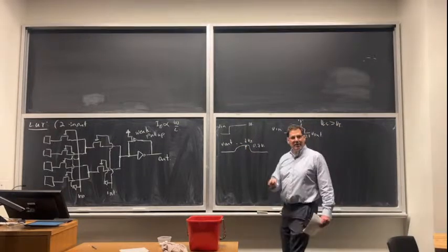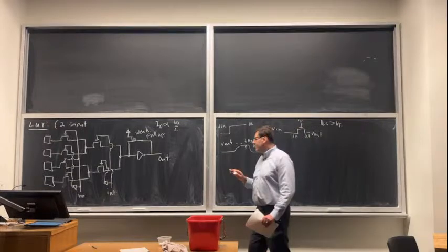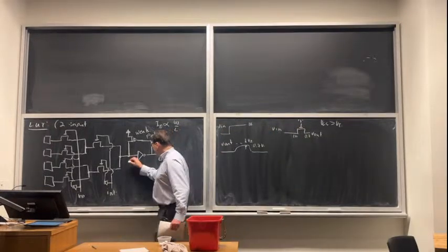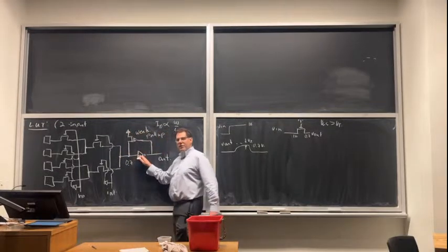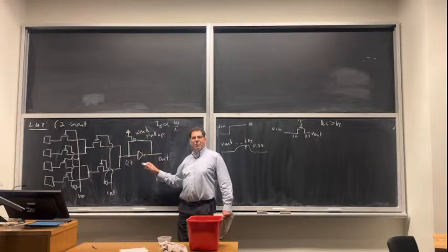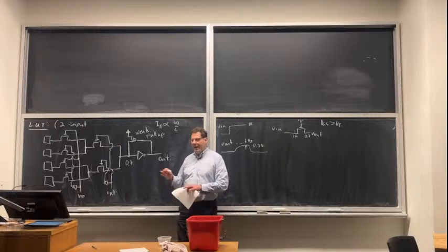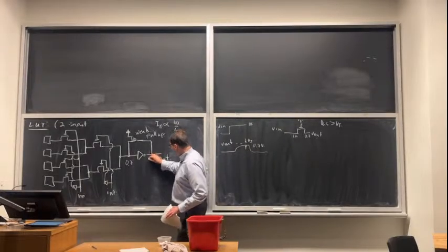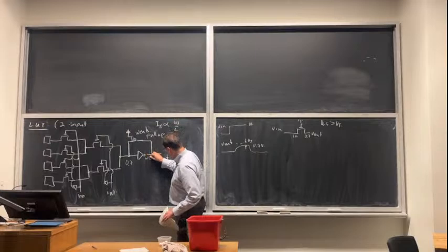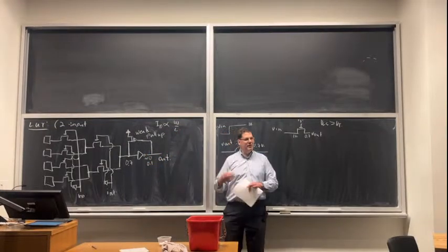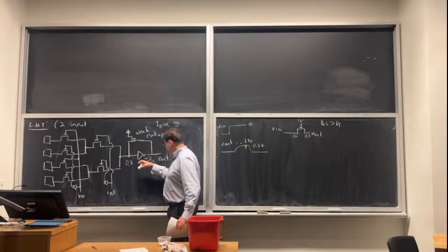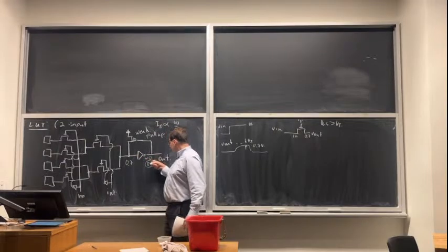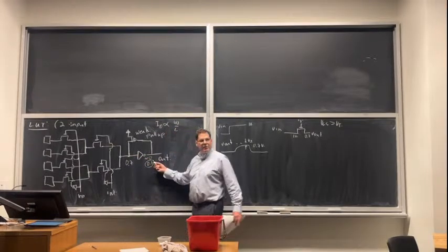Does that make sense? Okay, so if I took that 0.7 volts and I just said, oh, I'll live with it, I'll put it into this inverter. The inverter is an amplifier, so it will tend to amplify this, so the 0.7 will probably come out to be approximately 0, but maybe it only comes out to be 0.1. Right? It's going to invert it, and it's going to tend to amplify. So that's not great. My logic 0 may still not be at 0 after inversion.